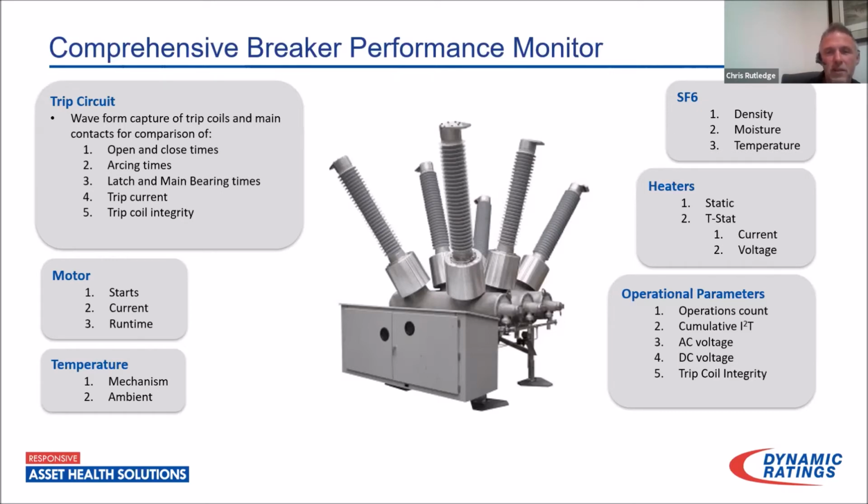However, when you start getting into hydraulics and pneumatics, it's a little more complicated in determining, is that motor run correct? With hydraulic mechanisms, you tend to see motor runs occasionally that are not associated with a breaker operation. This is due to changes in ambient temperature, and as it gets cool, that system will lose pressure, and then you'll hear that pump run to charge it back up.